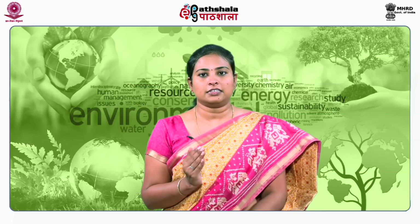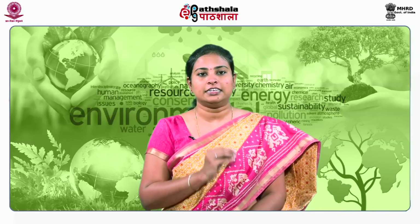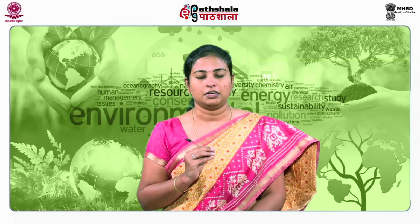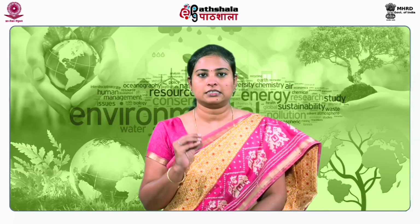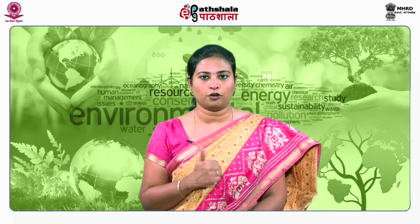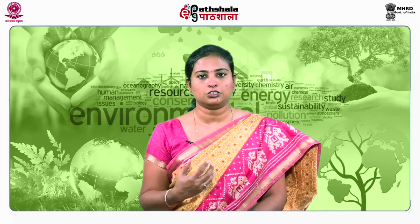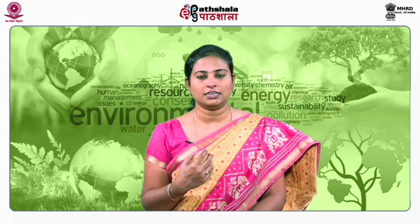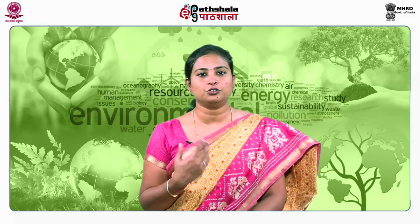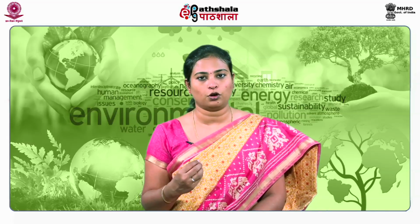So, in an activated sludge process, oxygen is provided in the aeration tank as the leachate flows into the system. The microorganisms present in the system thrive in the tank and form biological flocs. The microorganisms in suspension start consuming the organic matter in the leachate and transform it into new microbial biomass, in addition to producing carbon dioxide and water.